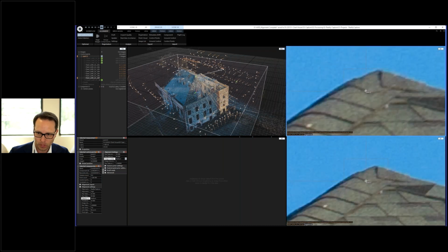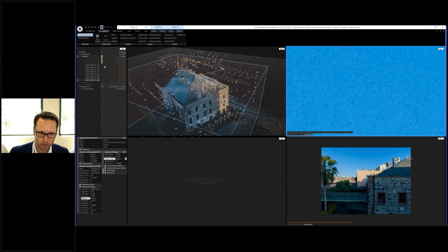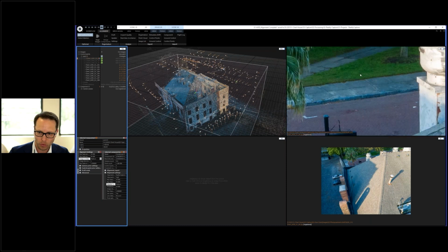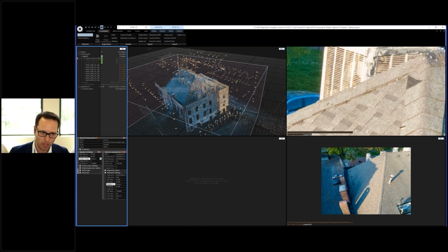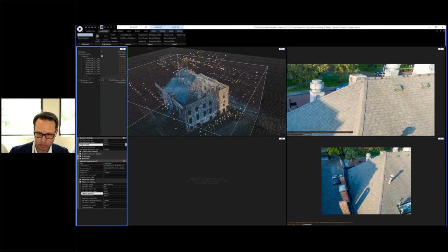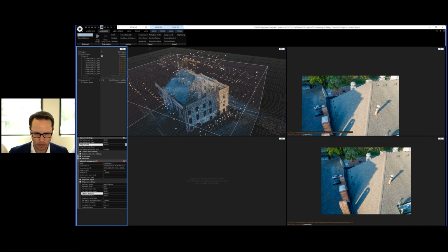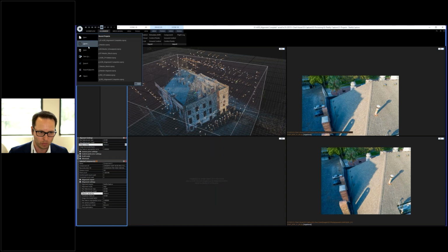All right, so this is the process of adding your control points when you try to resolve a misalignment within one component. You have a few more; you can either add these ones as well, or, if this is not a good one, you can just discard them. You follow this process until you've added quite a few control points. I forgot how many I added to correct this mistake, but what we can do is close this project and then open the project with all of the control points added. And I believe we fixed that issue very easily.